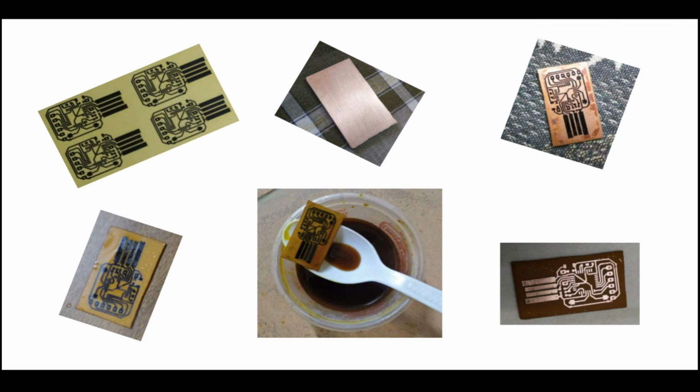Then you apply some heat using an iron box. People also use laminators to get some heat. You place it correctly and then apply a lot of pressure, for like 4-5 minutes. If you're lucky, if you soak the whole thing in water for 5-10 minutes and peel off, the whole circuit should be transferred. This comes with practice, but you try, and definitely within a day's time you will understand what you have to do with the components available. You can have this. The next step is